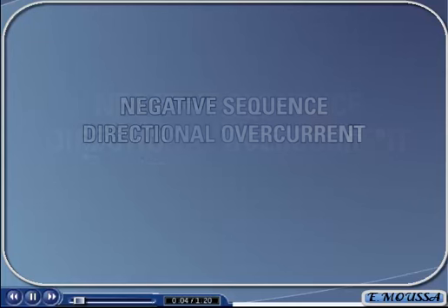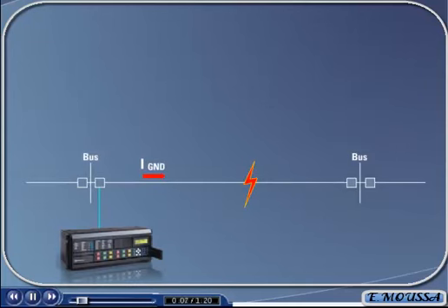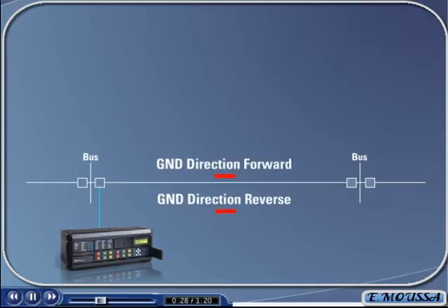When a fault occurs on a transmission line somewhere on the line, currents are flowing to ground. Measuring the direction of the flow of the ground current is used to assist some of the pilot-aided distance protection schemes in determining if the fault and the source of the ground current are located on their transmission lines. The ground directional overcurrent elements let the pilot-aided schemes know if the ground current rises above a minimum set level, and if it does, what direction the ground current is flowing. The ground directional overcurrent elements are used by the pilot-aided schemes because they are sometimes more sensitive to detecting faults than the distance elements are when the source has a weak infeed or high system impedance ratio.